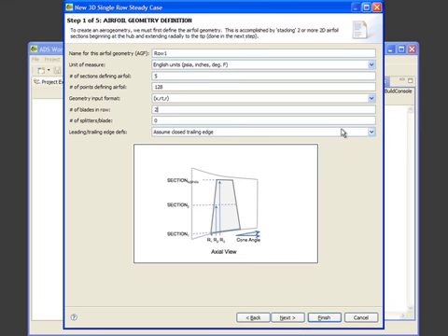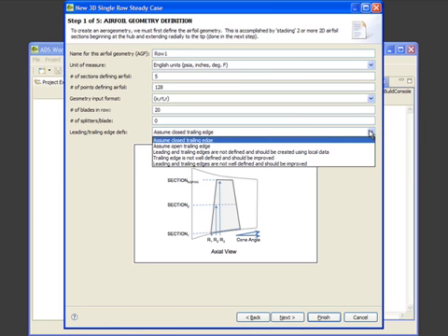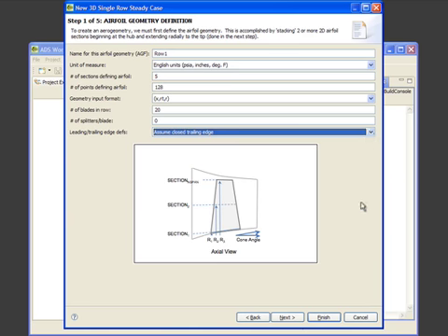The number of blades for this particular row is 20, and the number of splitters for this particular case is none. It should be noted that the number of splitters is a ratio on the leading and trailing edge definitions, and most of our users find that the leading and trailing edges are well defined. However, the ADS tool suite does allow you to enhance the edges automatically for you. You can refer to the tech reference for the options.